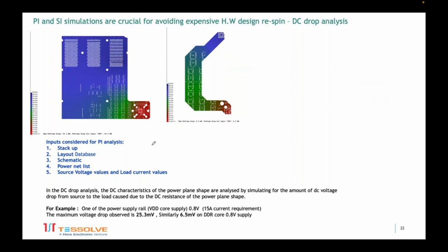For example, high ounce copper in the PCB traces, exceeding 1 ounce, could be considered. Even if that is not enough, you could look at sandwiching a similar shape in the adjacent layer and stitching with vias, so that the DC drop can be kept minimal, so that we don't throw away devices because of the load position issues. Plane impedance, one is the DC drop, the other one is the plane impedance.